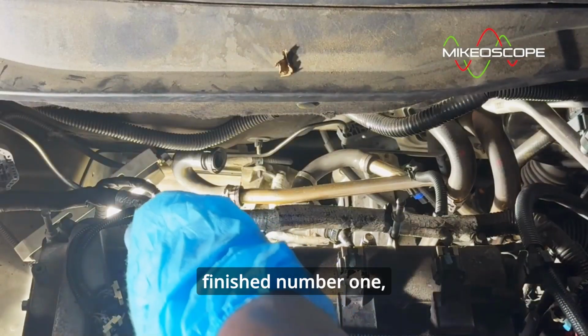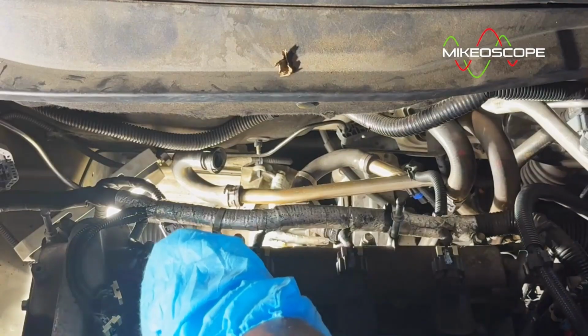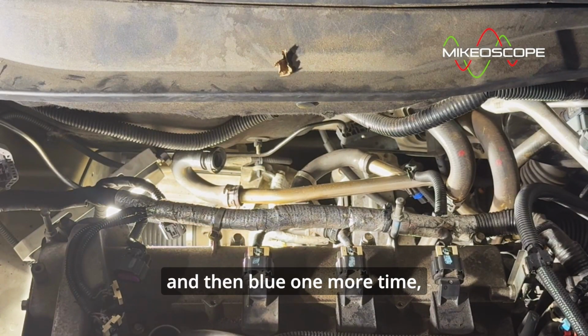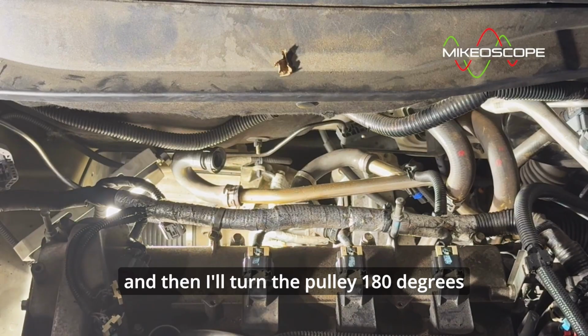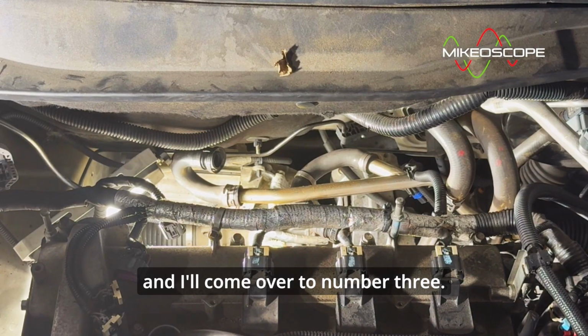Remember guys, I just finished number 1, so I'm gonna have to go to number 3, then 4, then 2. But before I move on, let me scrape it a little bit more and then blow it one more time, and then I'll turn the pulley 180 degrees and I'll come over to number 3.